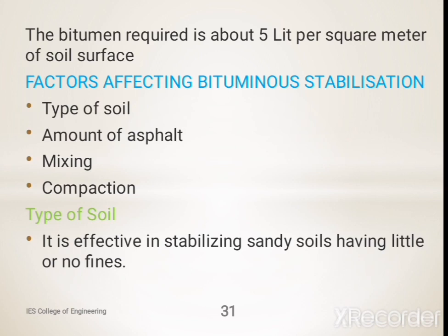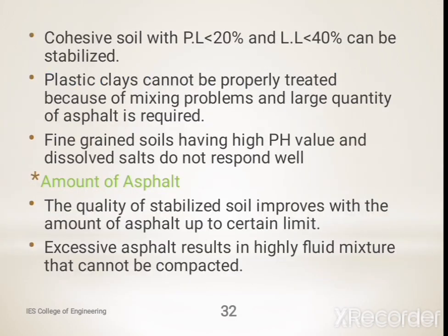The first factor is type of soil. It is effective in stabilizing sandy soils having little or no fines. Cohesive soil with plastic limit less than 20% and liquid limit less than 40% can be stabilized. Plastic clays cannot be properly treated because of mixing problems and the large quantity of asphalt required. Fine grained soils having high pH value and dissolved salts do not respond well.